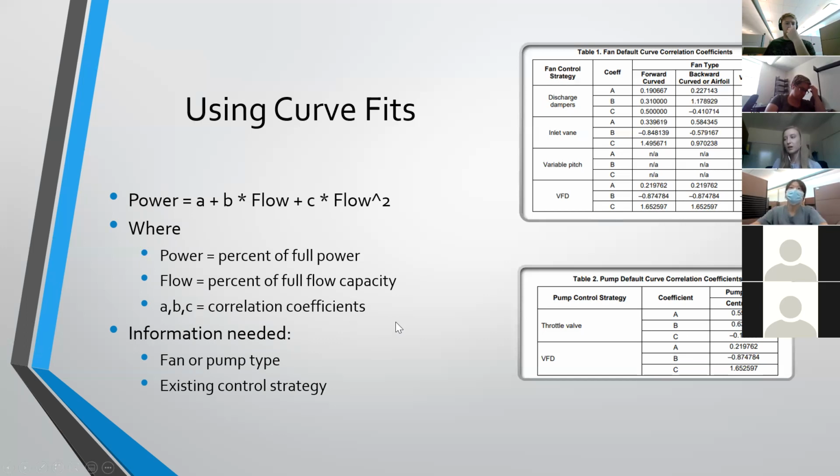Yeah, I think this is just a pretty simple, straightforward way to estimate your power usage. And don't forget that it's giving you percent of full power, so you still need to multiply that by your motor horsepower in order to get your actual power usage.